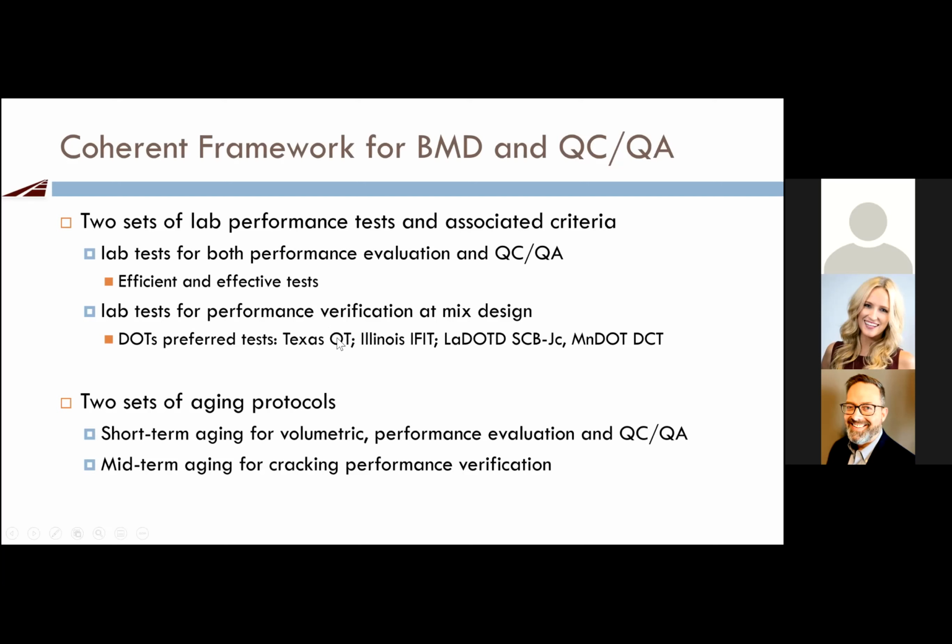Like Texas, you can choose your overlay tester. Illinois, I-FIT. In Louisiana, you can choose your SCB, JC. Minnesota is using the DCT. So this is a really good part of performance verification.